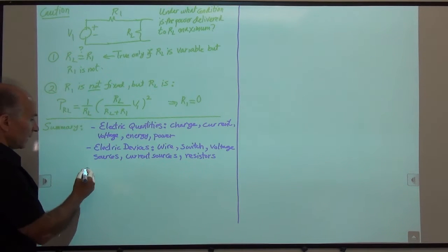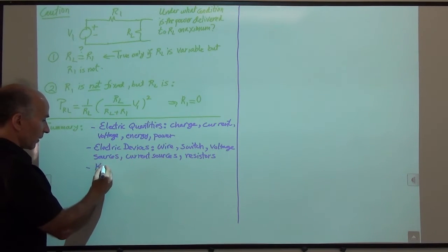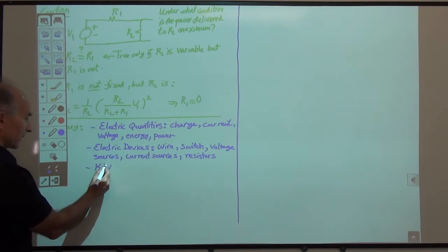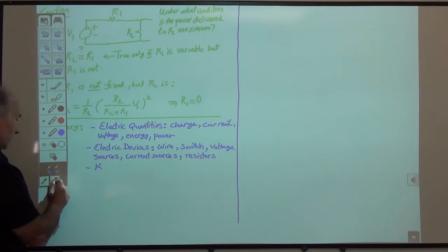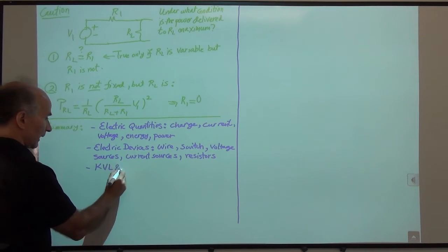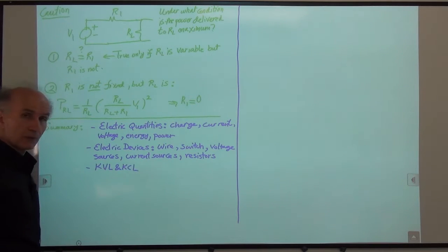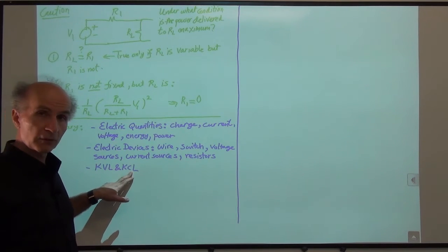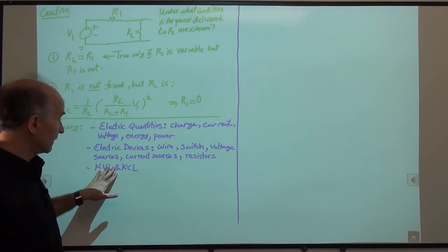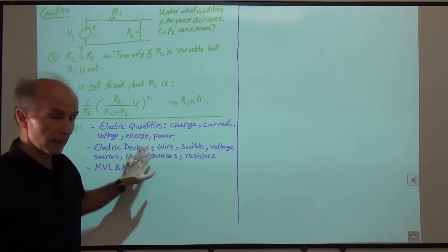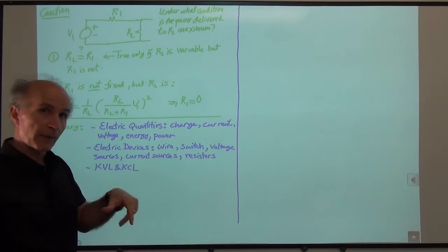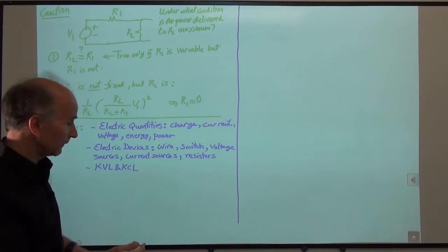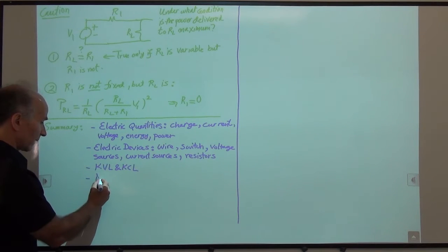All right, then we talked about the basic laws governing any circuit. KVL and KCL. So we saw that the sum of voltages around any loop should be 0. The sum of currents flowing into any node should be 0. And with these and the equations governing our devices, we can solve any circuit. But then we try to make this solution procedure more methodical. And for that, we looked at node analysis.